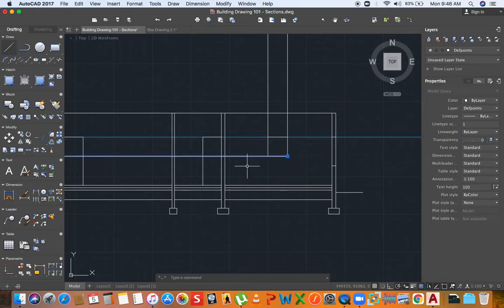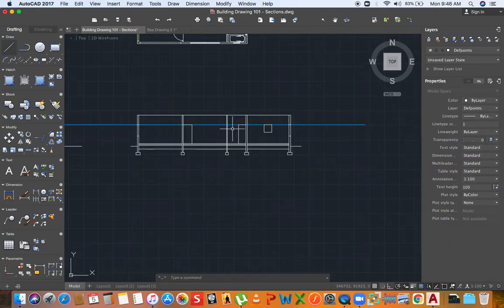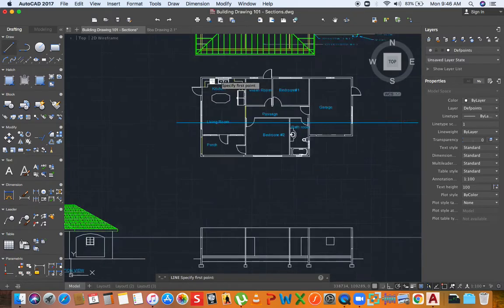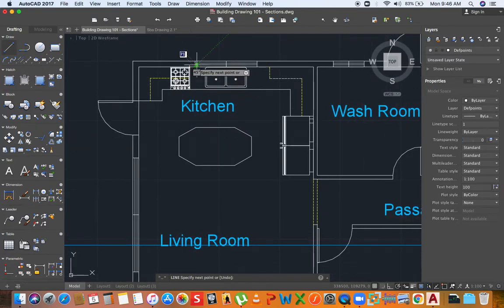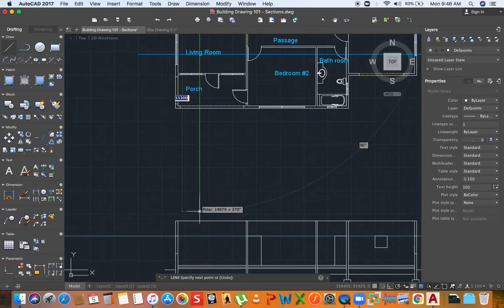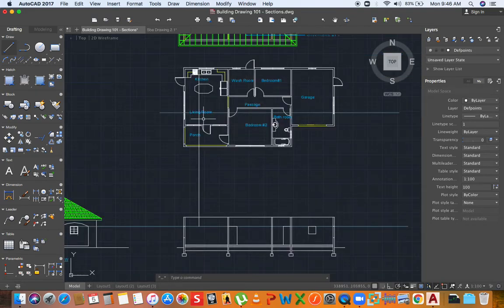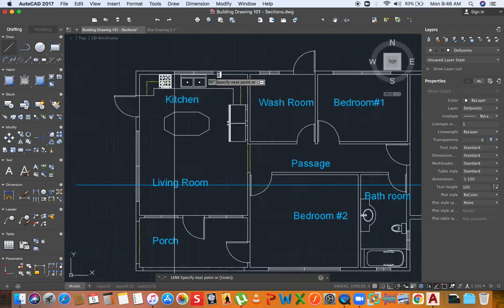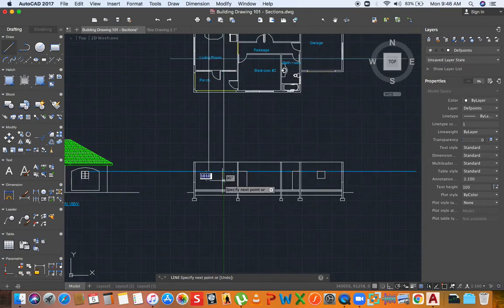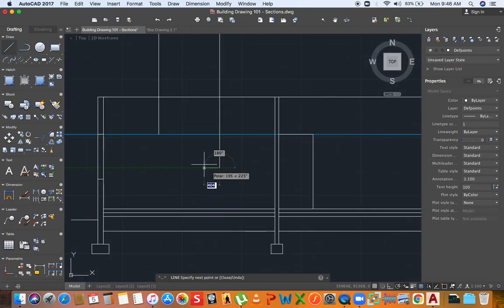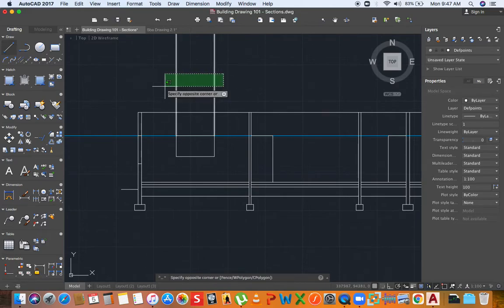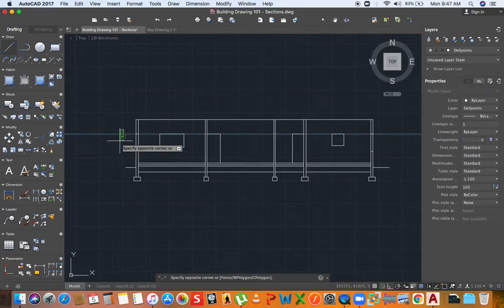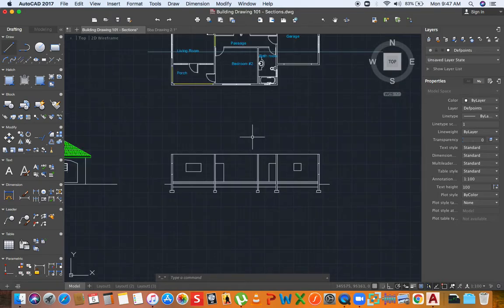And I'll go ahead and delete this. In the kitchen, I'll be seeing this window here. And I know the windows in the kitchen are normally brought down 900 millimeters. It doesn't go as far as 1,200 because you have to consider the counter. You don't want it to go below the counter level. It has to be higher than the counter level. Alright, so I think I'm through with this line here. I don't think I need it for anything else. Then I'll delete it. So this is inside of the building.